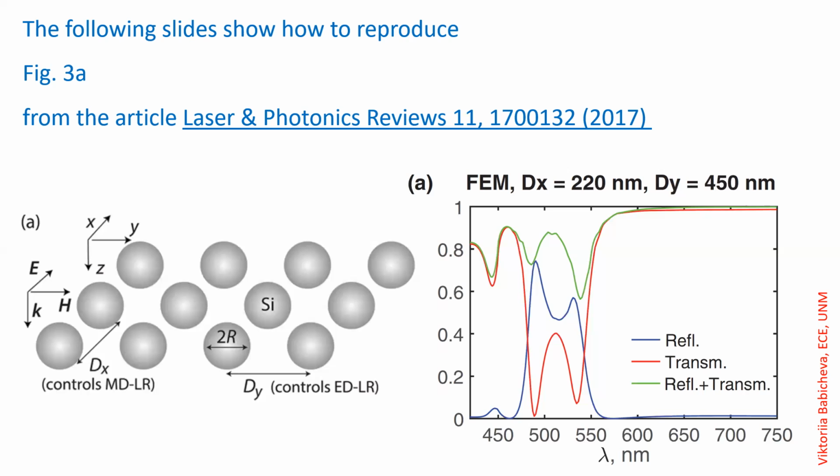An alternative option for simulation setting is simply to put numbers directly in the dimension boxes. But this approach can create many problems if we need to change any of the dimensions later in the process of simulations. Each time we need to change one number such as object dimensions, we have to go through all structure elements one by one, open those setting boxes, and manually change the number in each box. This process may take a lot of time and introduce more errors in the simulation settings.